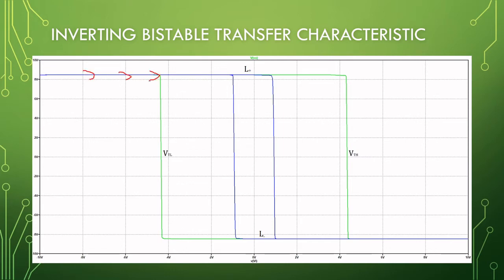Our input down here can be any voltage in this area above and the output will not change. But the moment that we reach 1 volt for our input, so this is all negative voltages, the moment that we reach 1 volt, the output will jump down to this negative state. And then our input can be any voltage from minus 1 volt up to wherever without this thing changing states.